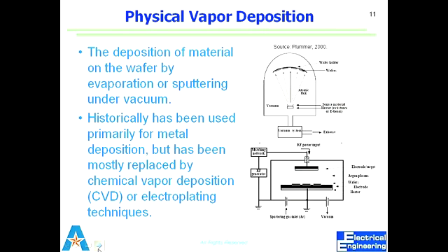In that case, the etching, we had that plasma generated and we were making ions travel to the wafer and they react with this chemical and etch the material away. If we change the recipe and we have something which, when it gets to the wafer, instead of etching it, gets adhered to that surface, that's called deposition.